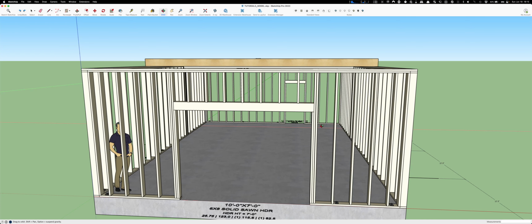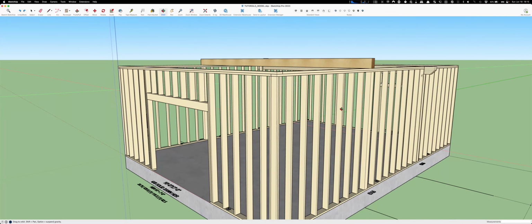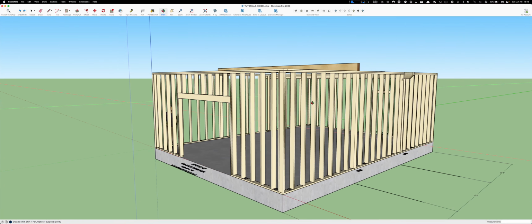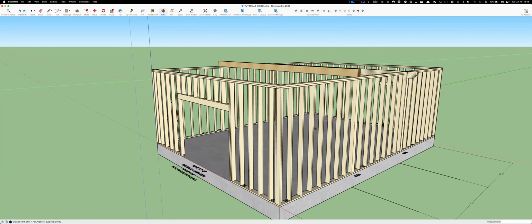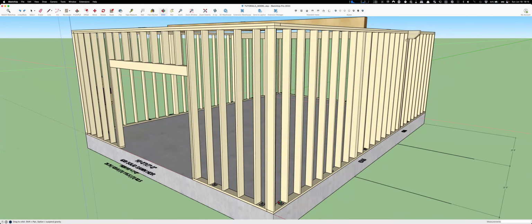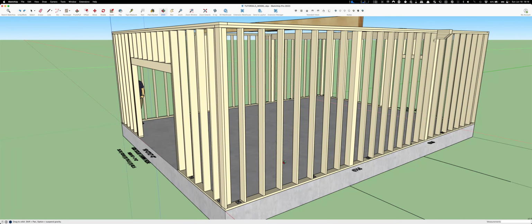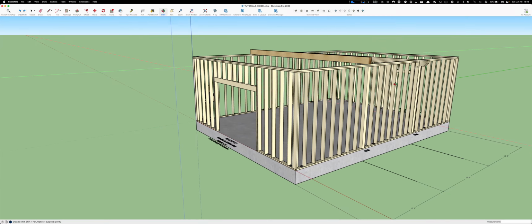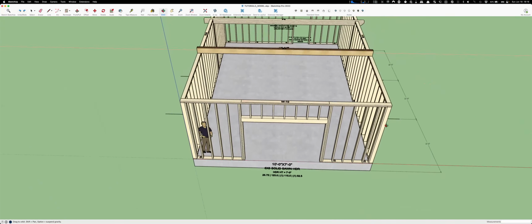So, I mean, I don't know if you need them, but it's been spec'd, so that's what I did. Frame as you're told to frame by the engineer. You can always go more, you just can't go less. So he's got the Energy L corner right there, where they can tuck insulation in behind. This guy's good. I like him.